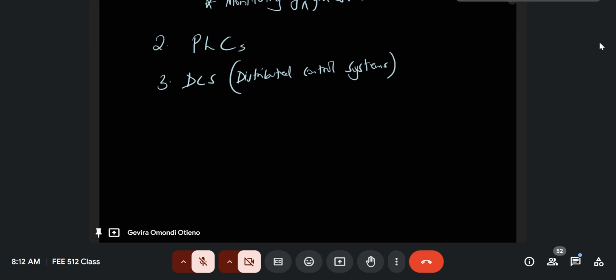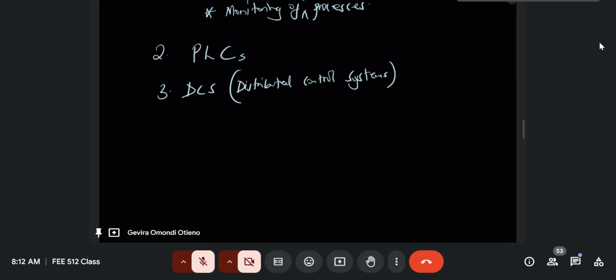So they have a distributed control system that allows the automation to be on a large scale. DCS is over a larger scale than PLCs, because PLCs are centralized to a location or within a network, but DCS, or distributed control systems, are not centralized. They're distributed throughout the system, so that you are able to interface several computers and even several pieces of equipment and configure them, but over a wide range of systems and, of course, locations.